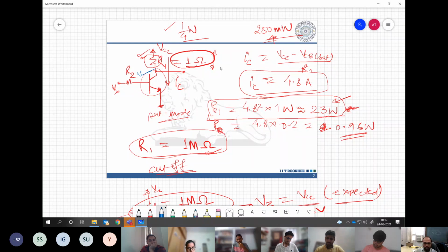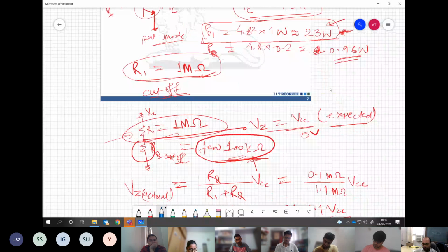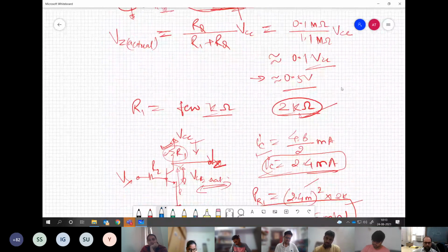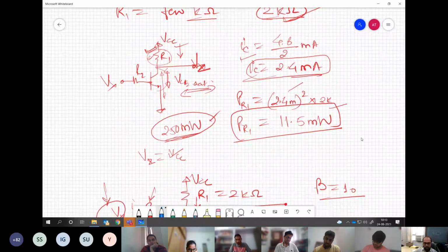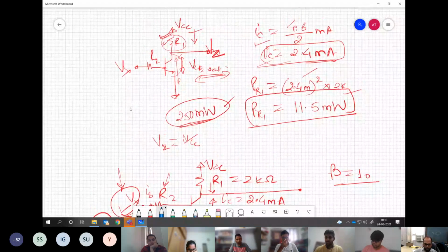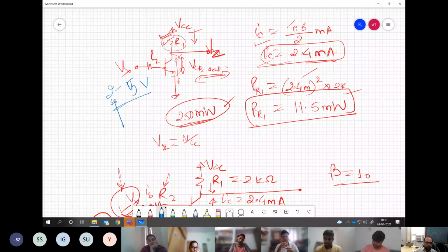So we have seen what should be the values of R1 and R2, how should we choose that, so that even for the worst possible input, I mean the lowest range for the high input, so if you are saying 2 volts to 5 volts, the lowest voltage would be 2 volts, up to this, the circuit should operate perfectly fine. So that is the purpose of designing.